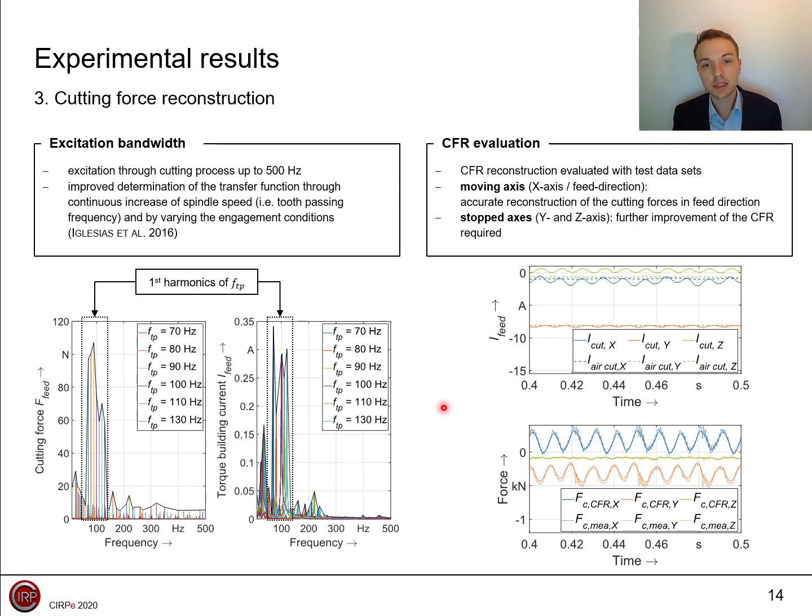As the two frequency spectra on the bottom left show, excitation by the test up to 500 Hz can be observed in the dynamometer measurement and in the motor current traces. It can therefore be assumed that the calculated transfer function enables the reconstruction of the cutting forces up to 500 Hz. Additionally, Iglesias et al.